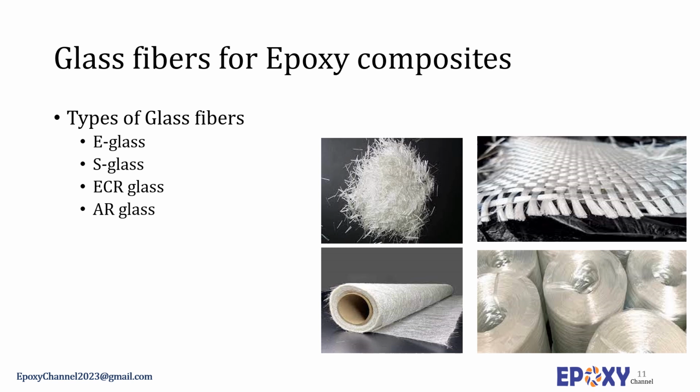The fibers are often prepared by drawing from a bushing below a molten glass reservoir. The most important and commercially sensitive stage in the process is the surface treatment or sizing, which is applied by rubber roller prior to assembly into rovings. The rovings can be either used directly, rewound onto a bobbin for further textile processing, or chopped into short fibers for the production of chopped strand mats.